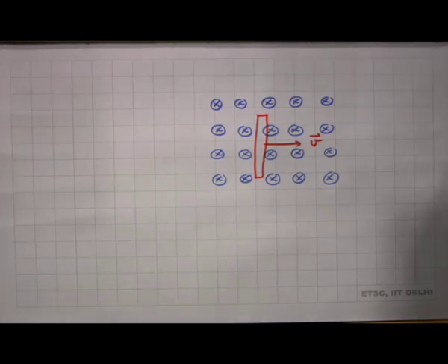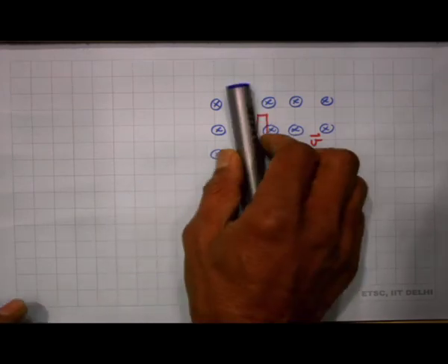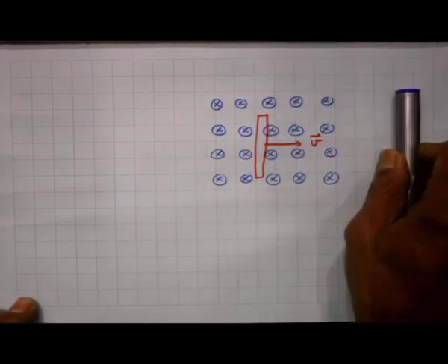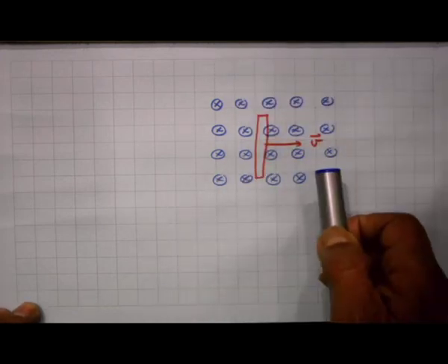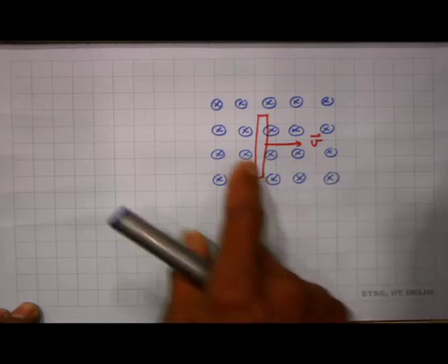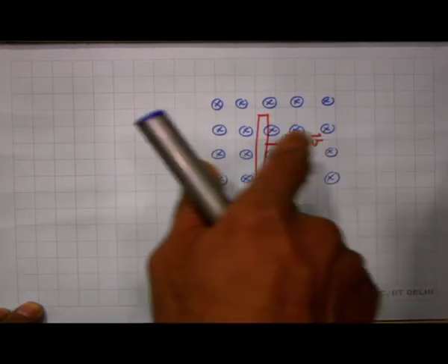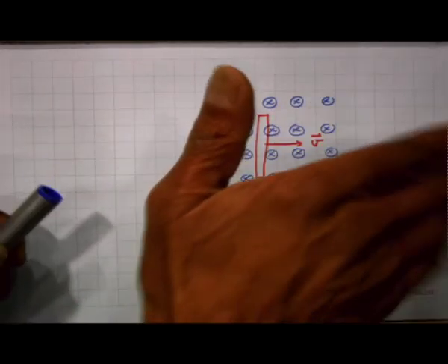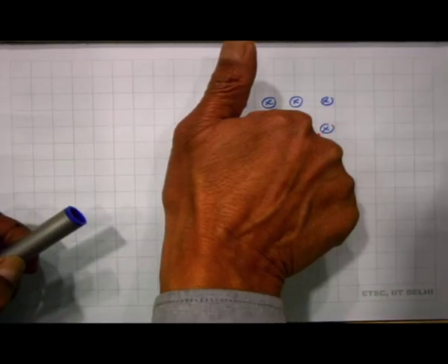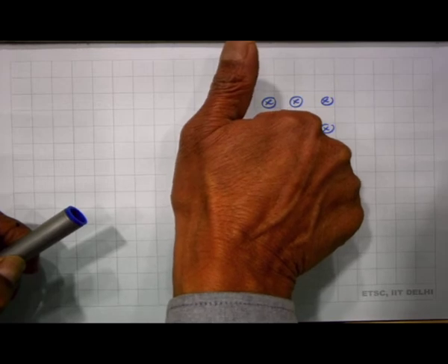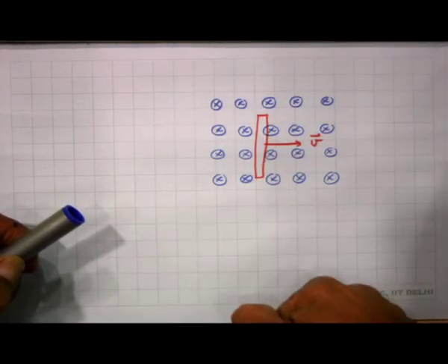Now, what is going to happen? There are electrons in the conductor, and when I move the conductor, the electrons start to move. Motion of a charge in a magnetic field will induce a Lorentz force on the charge. So, for an electron moving like this with a magnetic field pointing downwards, V cross B is upwards, but because the electron has a negative charge, the force is downward.